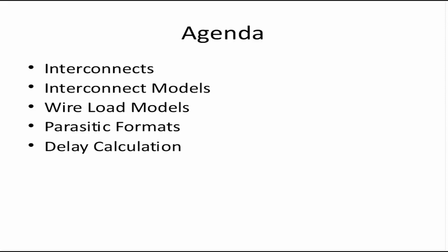The cell delay comes from the library. We all know that, actually in the NLDM format. The delay numbers are represented in lookup tables, and a tool like PrimeTime just has to do interpolation based on the input transitions and output loads.